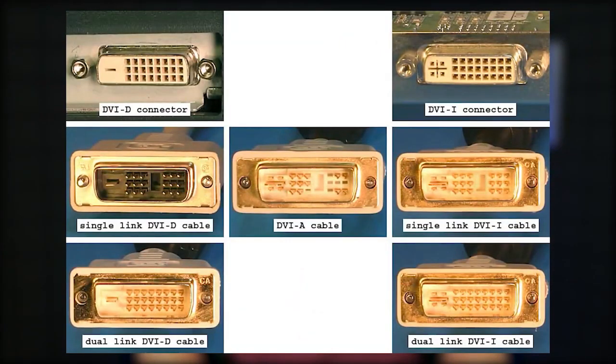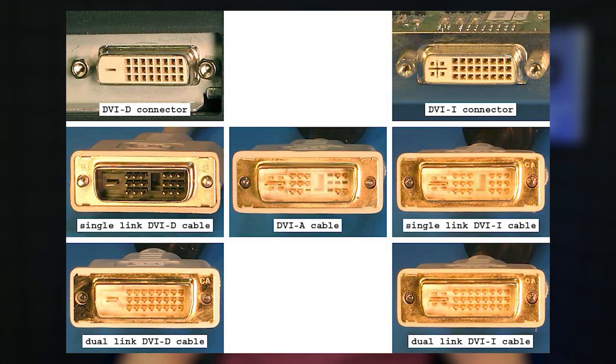If your computer or laptop has a DVI port, which is quite rare nowadays, you should find out what kind of DVI port it is – DVI-A, DVI-D or DVI-I, because it is important to choose an adapter or converter depending on the specific port you have. For example, if you have DVI-A, it is compatible with analog interfaces and the only option you get is VGA. DVI-D or DVI-I can be connected to HDMI with an adapter, which can be found quite often in electronics shops.